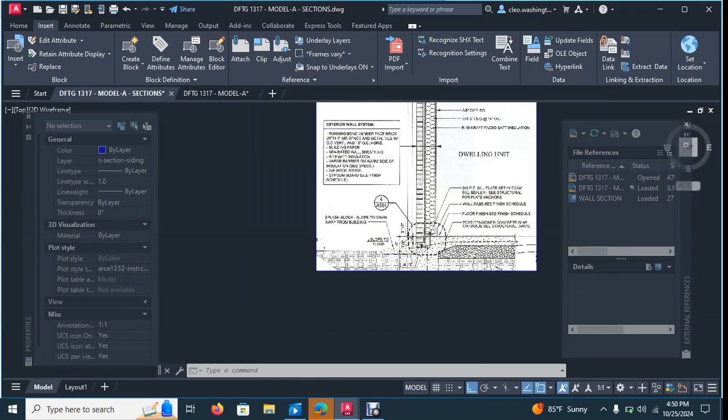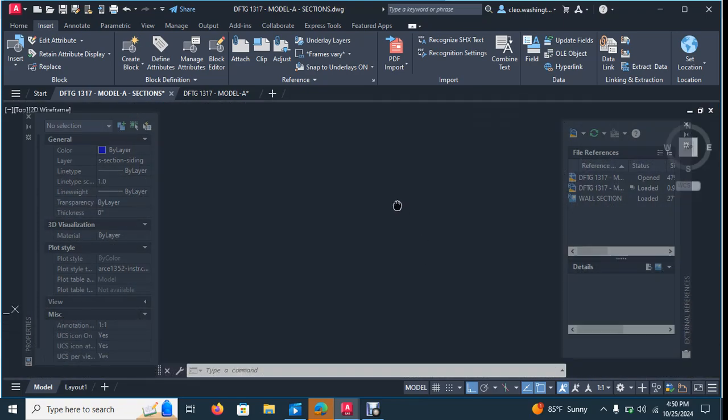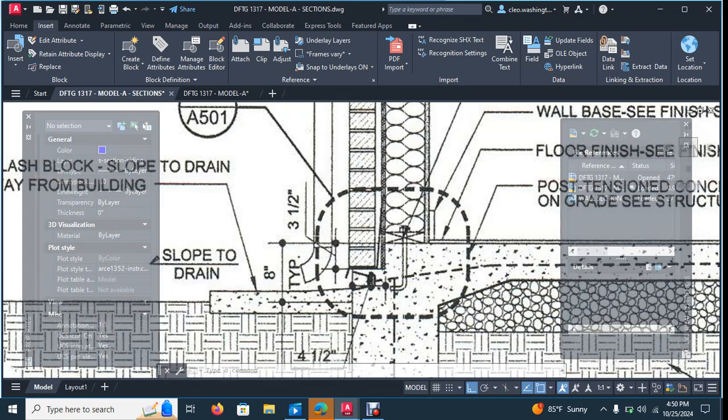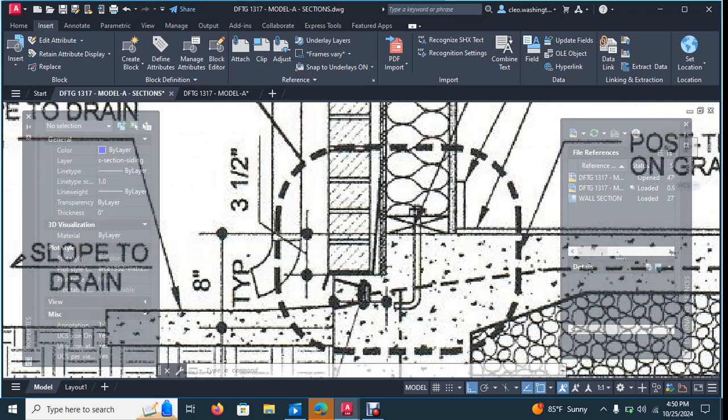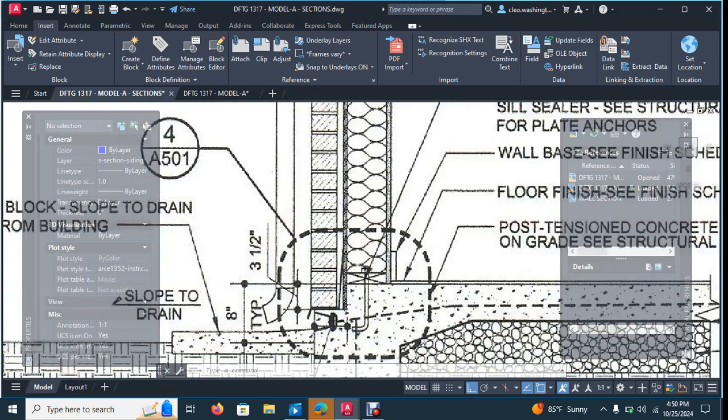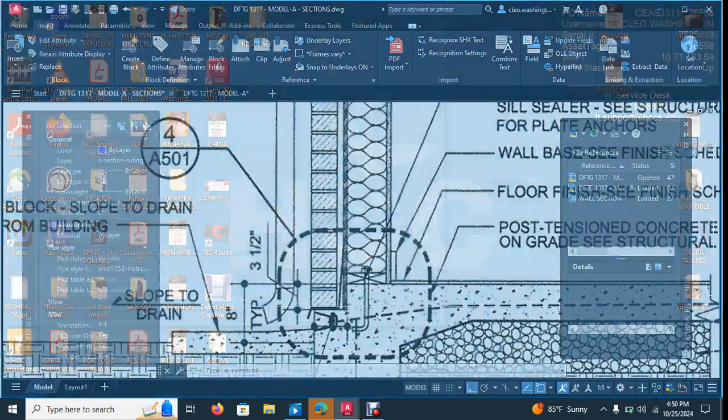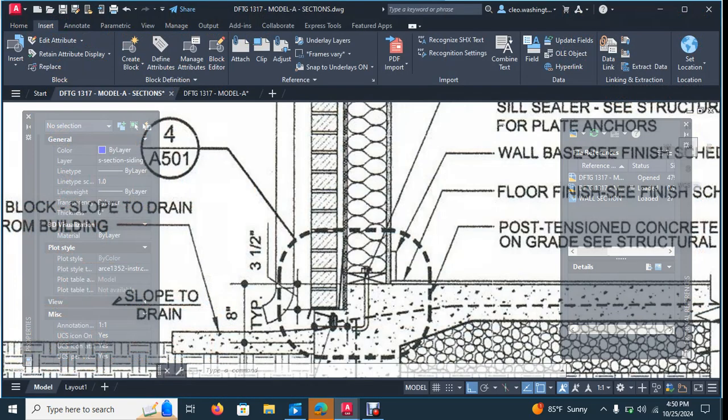So let's go ahead and start doing that. First things first, we have to show the exterior wall. We didn't show it on the original building sections. But when you do these wall sections, these blow up, you have to really show what's really there. So what's shown here? We actually have our 2x6 wall stud. And another thing, I notice a lot of people still have the 4-inch walls. All right, so we're going to have an exercise where we go back and put the 6-inch walls in. I know some of you guys started the drawings before I took over the course.